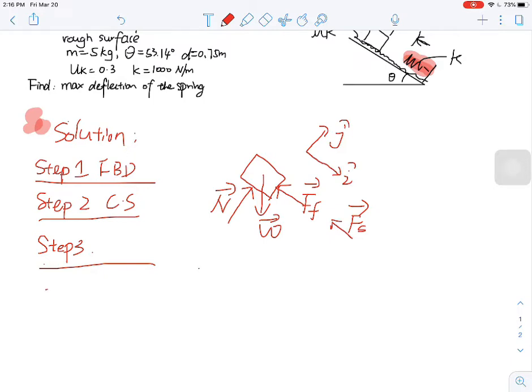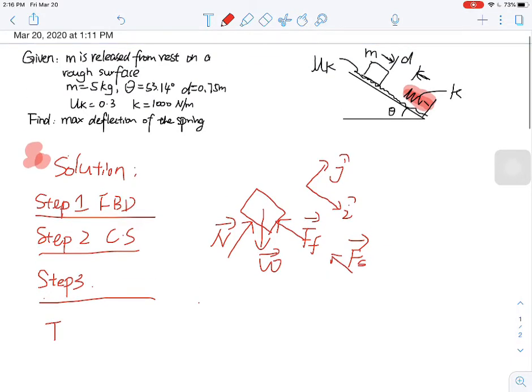So the kinetic energy in each mass. Here we only have one mass, the block, which is the only thing with mass in this problem. So we just need the kinetic energy of this mass at position 1, which is the time when it's released, and that is 0, since we don't have any speed at that time.